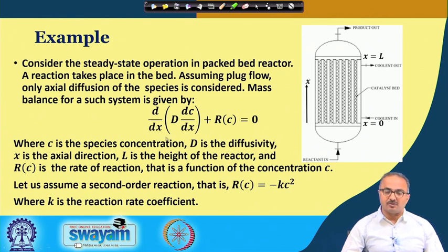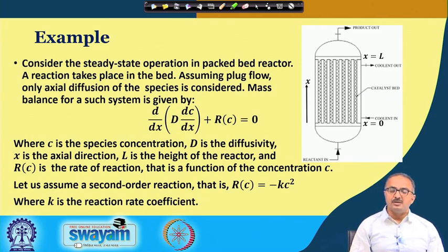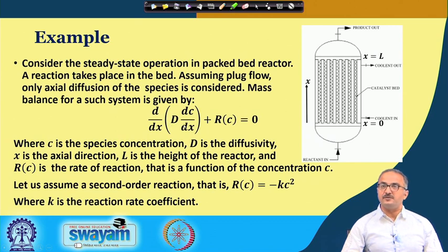And this is a diffusive term, and we also shall be having the source term, and because we have assumed this to be a steady state operation, there is no time derivative in the mass balance equation. Okay? So this is the diffusive term which is coming from the balance, and this is the source term which is also appearing due to the reactions of the particular components.